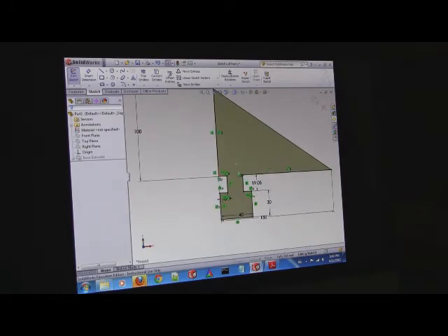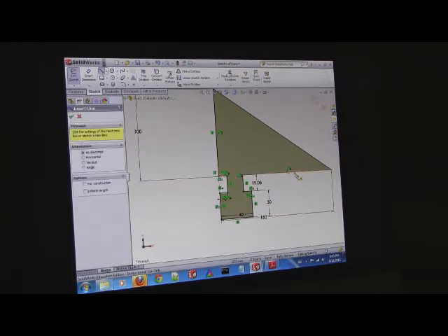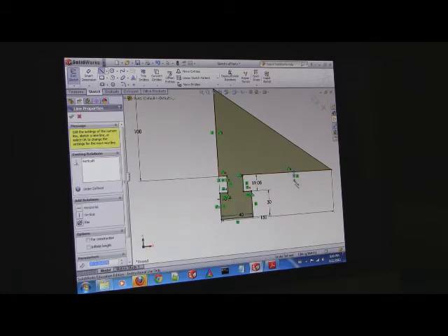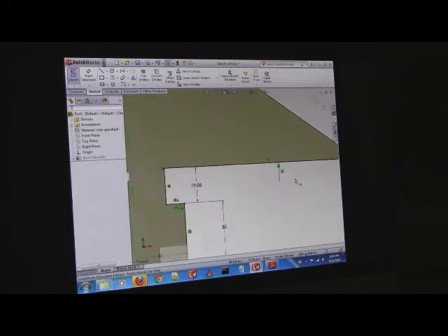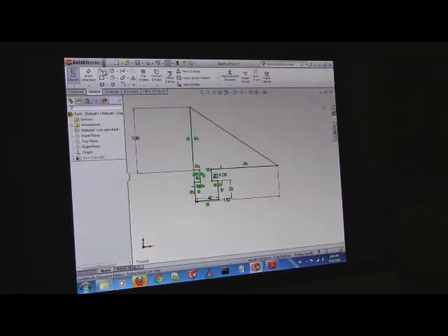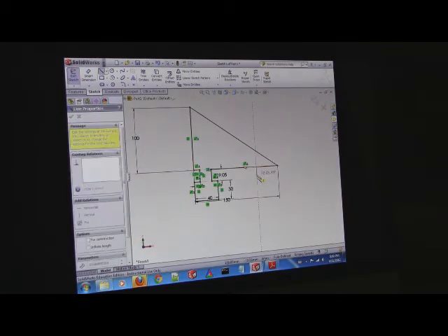We need 4 more of these. So I'm going to show you 2 ways of doing this. One is laborious, the other is not, but it's very dangerous. So first, go ahead and draw that rough sketch here. Now let me show you something. Eyes on my screen for a sec. When I click this down, you see how it wants to auto-align? That's usually not a good idea. SolidWorks does dumb stuff. If I get in this scenario where it wants to auto-align, I intentionally come up or down until it doesn't auto-align.